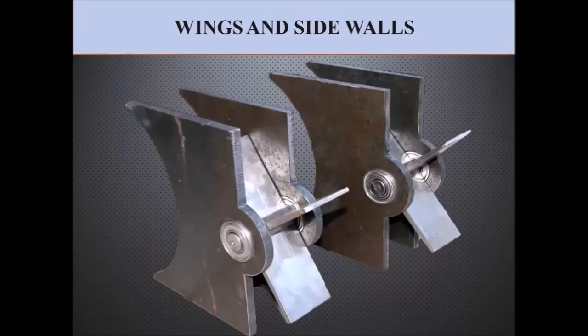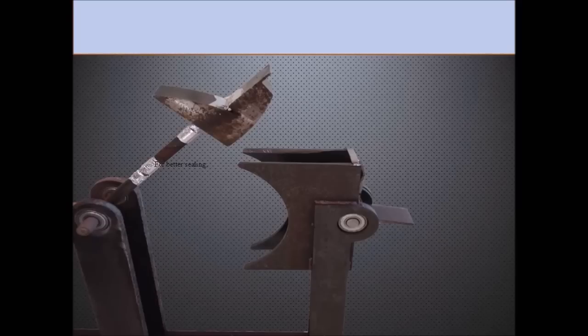To lubricate the engine, tiny pores can be placed on the inner side of the sidewalls and on the edges of the wings. Then all that is needed is to pump oil to these pores. For better sealing, the inner side of the sidewalls where the combustion occurs could be made a little thicker. Also, the edges of the revolving head and wings could be sealed with a sealing material.